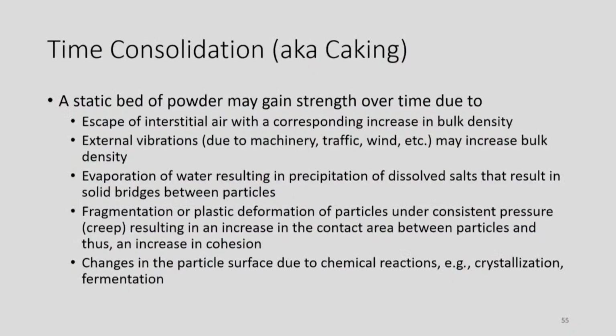Again, time consolidation is another factor, right? Most commonly we use bins for storing powders, or any granular material. Over a period of time, from its own weight, it adds strength to the powder, right? That's called time consolidation. Due to the increase in time at storage, many powders cake. You all know about caking, right? We briefly talked about it. Caking of powder is a big issue. When you increase the storage time, the powder can cake.